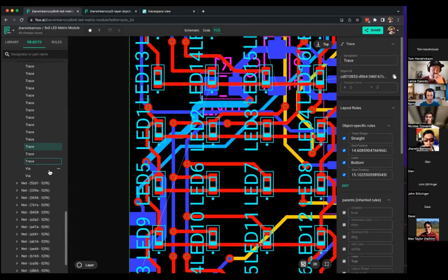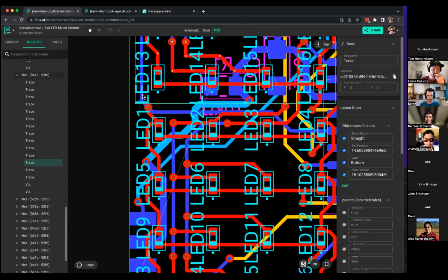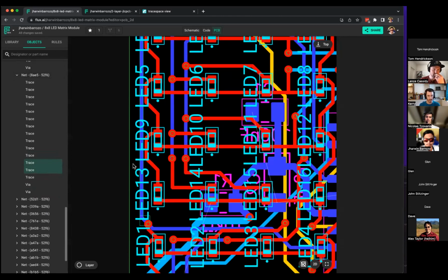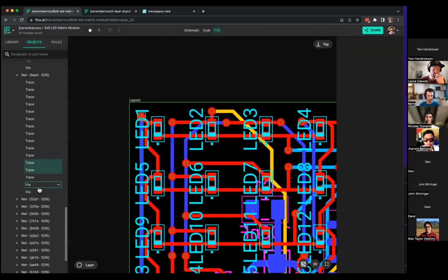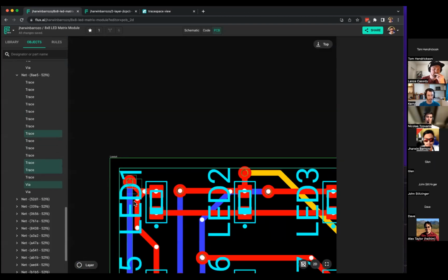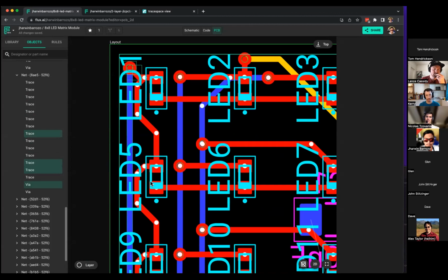And that's when I could select the top one, which is like, let's find that one. Yeah, that's it. Okay, then which one here? Okay, maybe the via, like that. And that red copper that connects that via, where's that? I'm going to hover to see where that is. Okay, that's it. And then I'm going to press delete, and that will clean up that connection.